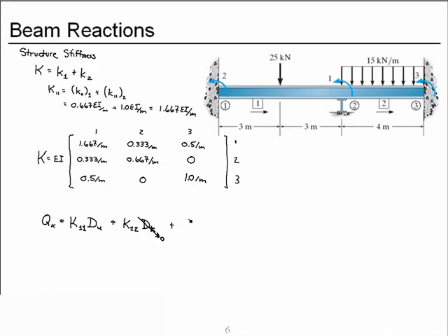But we also add our known loads, or load degree of freedoms, the fixed end forces. Once we solve this equation for unknown displacements, I want to point out the subscript 1,1 is different than this subscript. This referred to a single entry, the force at degree of freedom 1 due to deformation at degree of freedom 1.